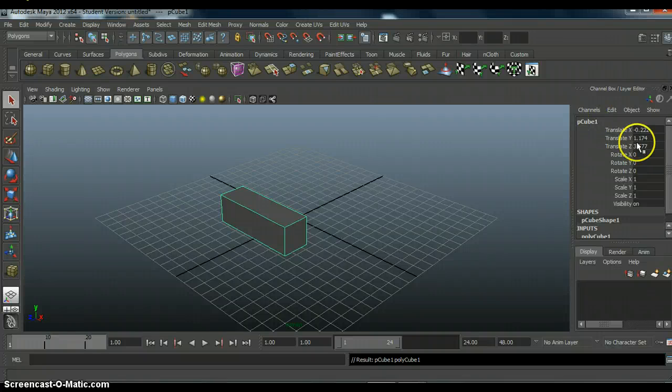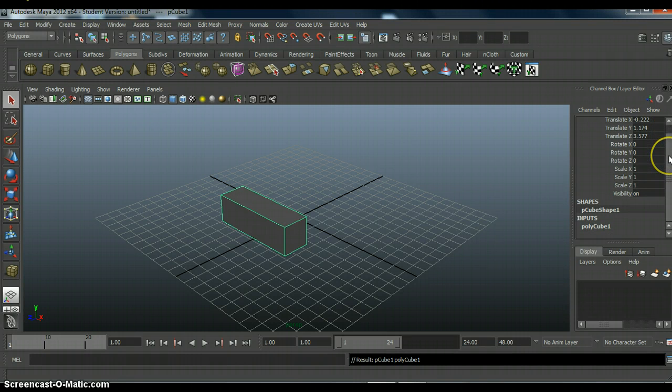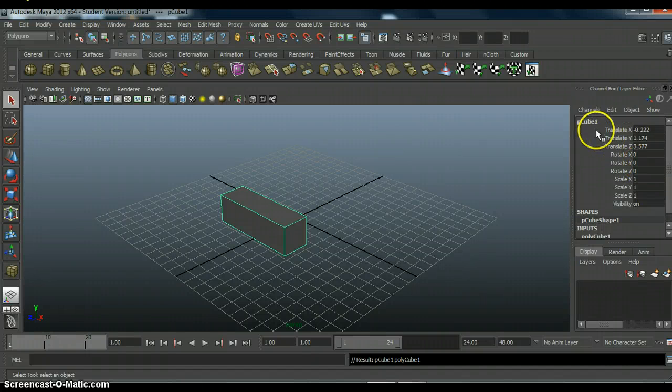So we can actually go into the attribute editor and adjust some of these. We can rescale our polygon with a lot more precision compared to, let's say, the scale tool itself, because we'll be dealing with numbers versus just pulling on one end of a tool and using your eye to adjust accordingly. But aside from that, yes, I will show you an example of that.